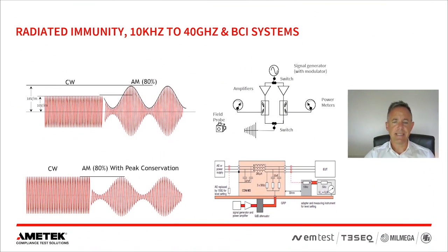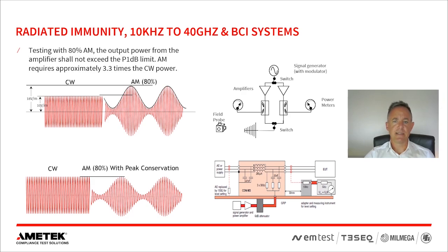For EMC testing, amplifiers are required to generate the field strengths and currents for immunity testing against the commercial, sub-6 GHz, medical, automotive and military standards. These standards define the requirements for the measurements, and as a result the requirements from the amplifiers such as output power, linearity performance, CW or pulsed operation.